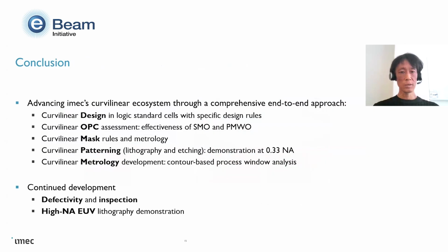So that brings a conclusion. In conclusion, this work presents a comprehensive end-to-end approach for the curvilinear enablement. We investigated the curvilinear standard cell design, OPC optimization, including the SMO and PMWO, mask rule developments, curvature methodology, and experimental lithography and etching demonstrations.